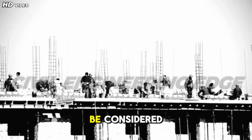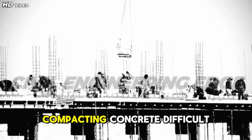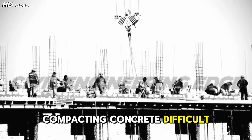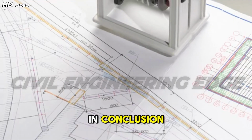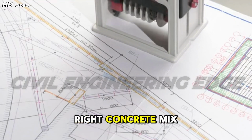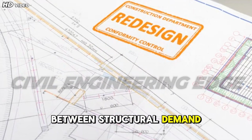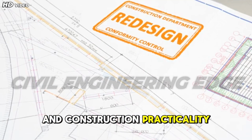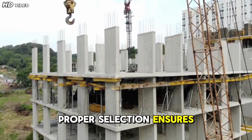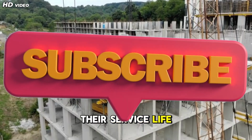Constructability should also be considered. Excessive reinforcement can make placing and compacting concrete difficult, leading to honeycombing and reduced strength. In conclusion, selecting the right concrete mix and reinforcement is a balance between structural demand, durability, economy, and construction practicality. Proper selection ensures that columns perform safely and efficiently throughout their service life.